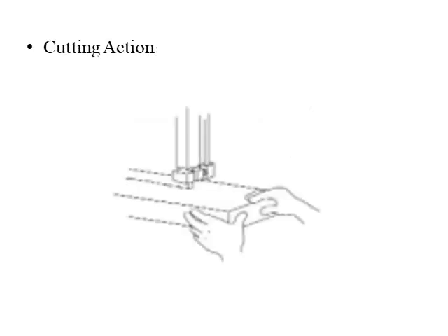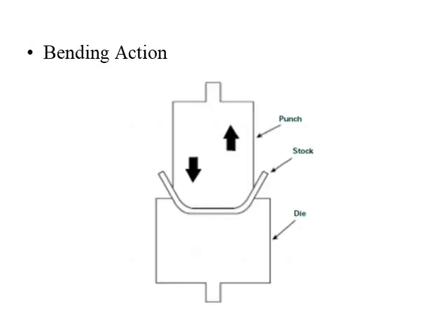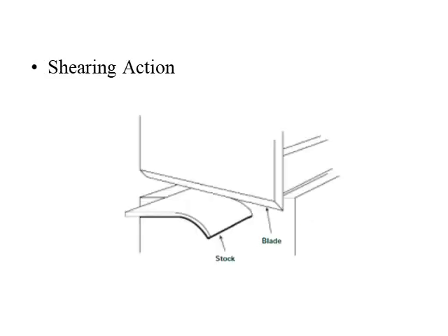Next, safety guards need to be provided during cutting action. Even during bending action, it is very important. Here accidents usually take place when the stock, or we can say raw material, is fed into the machine manually when we hold it, and when the punch comes down and moves, or when we remove or insert the raw material, it will prove hazardous.